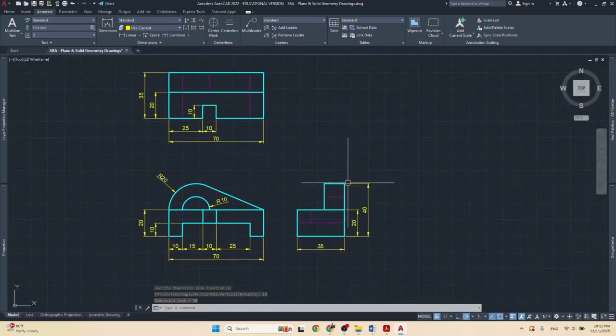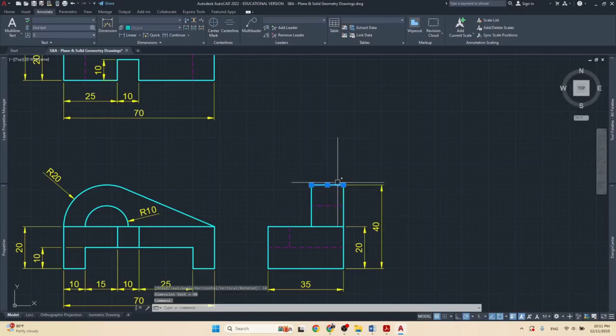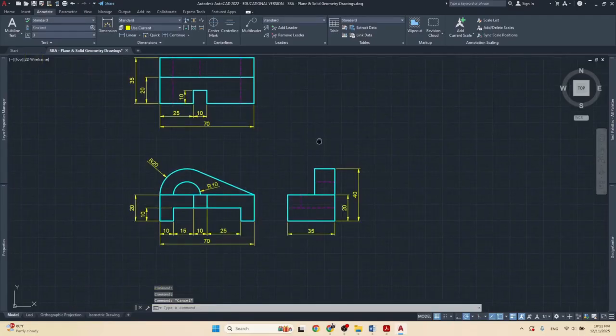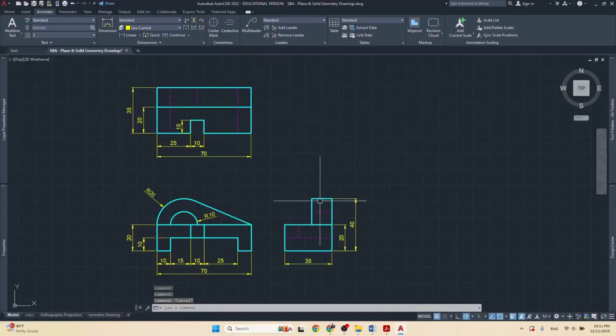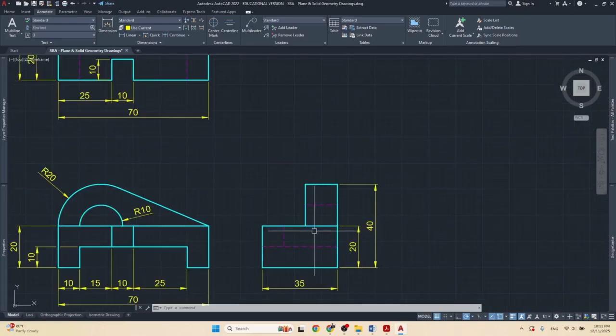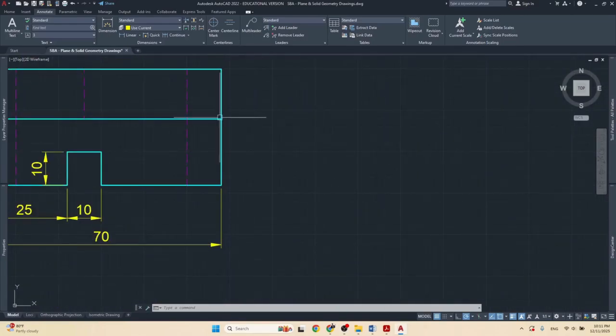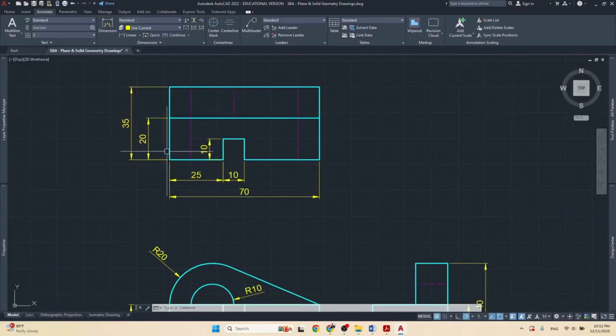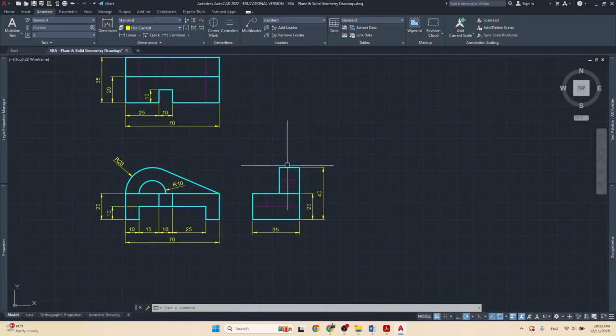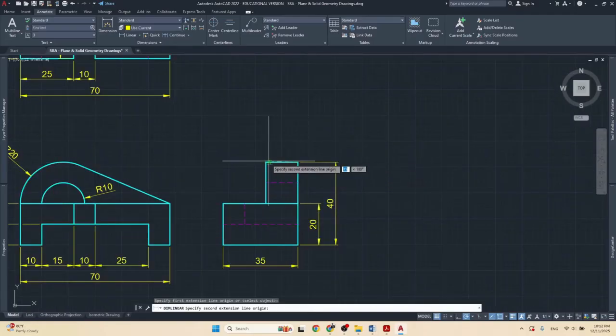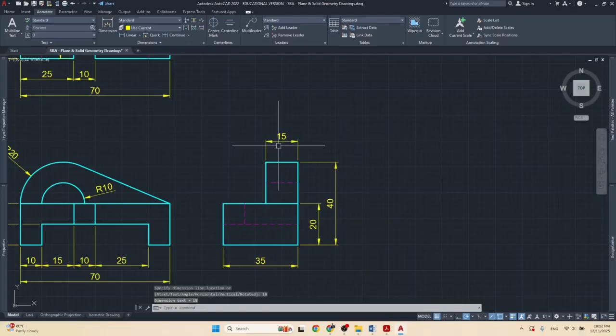Now, how wide is this? We know that this is 15, because if we come up here, this part is right here. Well, the width from here to here, that's right here, from there to there. And if we look over here, we minus 20 from 35, we're going to get that distance, which is 15. But let us show it, because it's not going to make the drawing messy and complicated in showing just that little detail right there. And because we know this is 15 and we know this is 35, then we could know that this distance right here is 20. Okay,